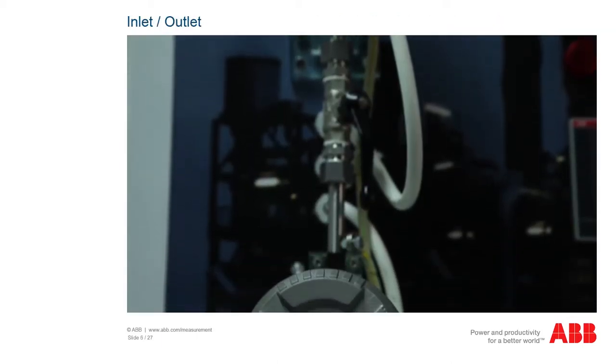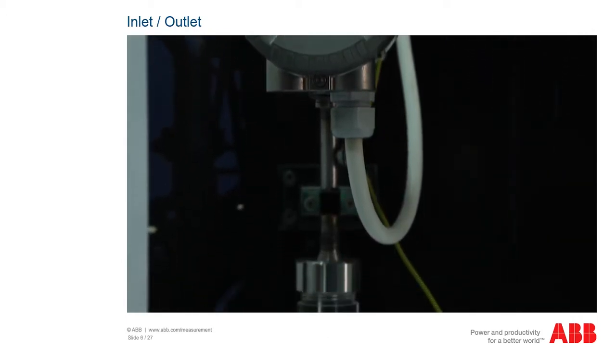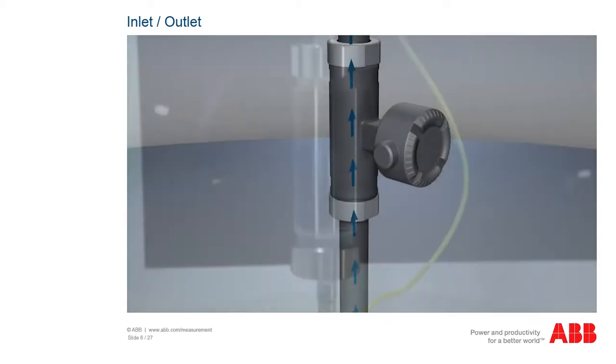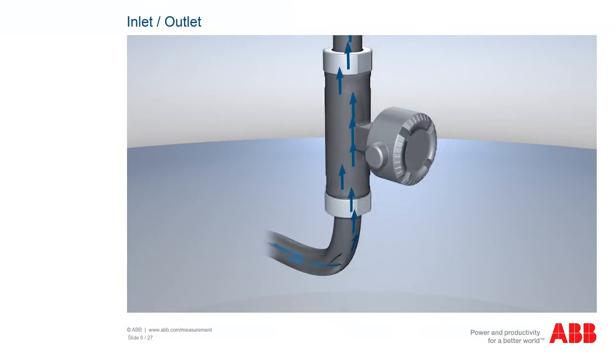The inlet and outlet sections from and to the flow meter are important. Why? I will explain this briefly. When measuring the flow, it is important that the liquid flows through the measuring system evenly. A pipe bend changes the flow profile of the medium. Because of inertia, the liquid flows out of the rear bend outlet faster than from the front area. This can lead to the flow meter measuring results showing values that are too high or too low.